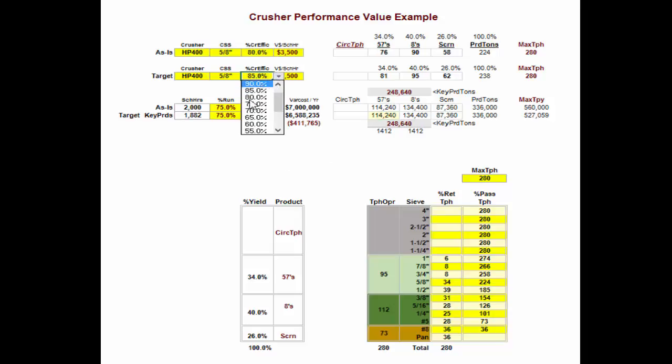If you take it up another 5%, you're at $750,000. Very sensitive issues: if you don't know how your crushers are actually performing efficiency-wise, you have no idea that you're losing that kind of value. With the scale system, that value, or the differential, would be seen in the recirculating load, among other things. One of the indicators would be an excessive amount of return material that comes to the screen and goes back to the crusher again.